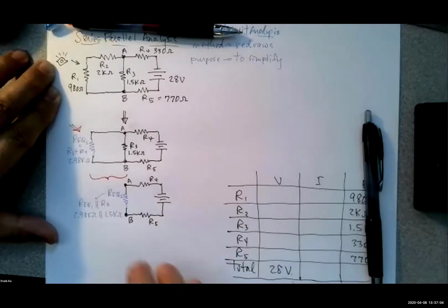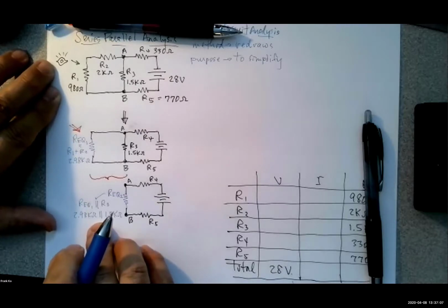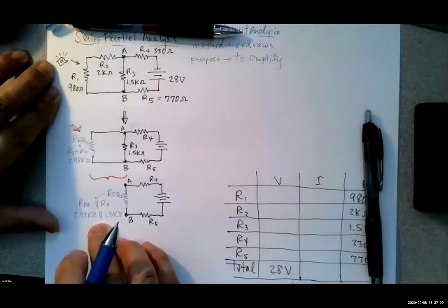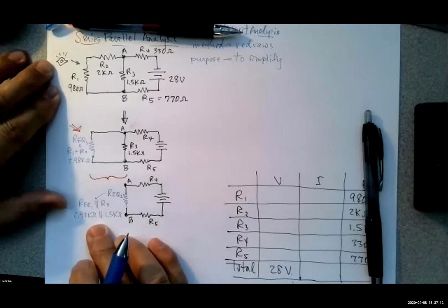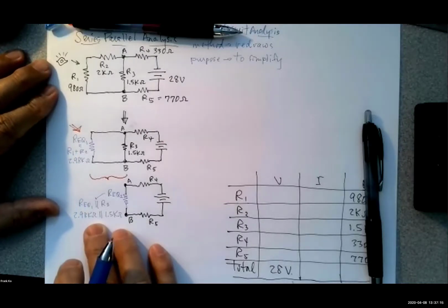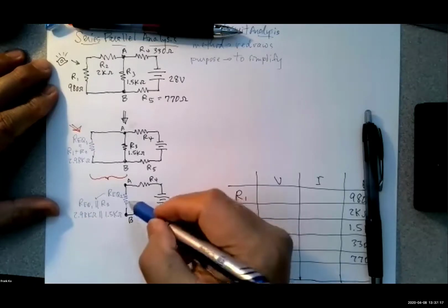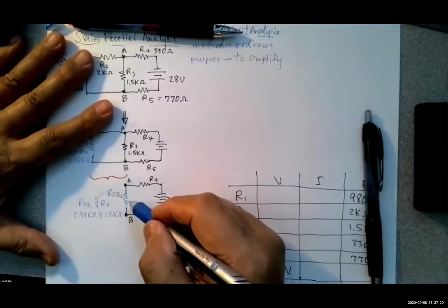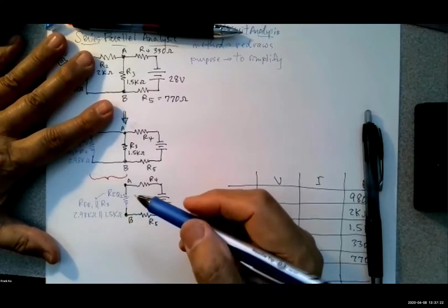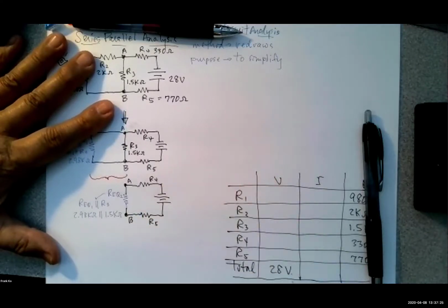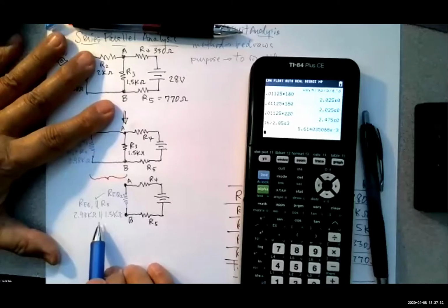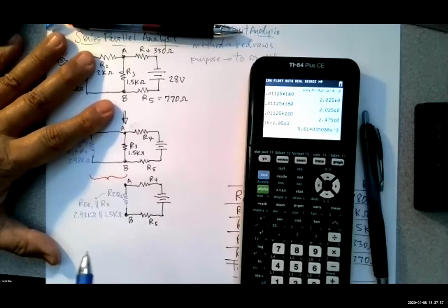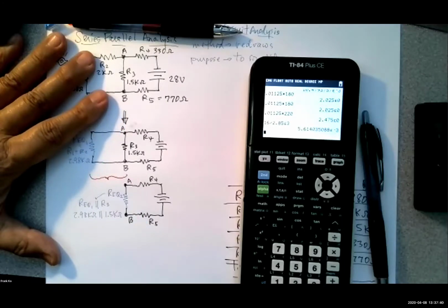So that being said, just off the top of our head, can we guesstimate some kind of a number for this? Question goes to Pauline. The result of these two in parallel to be a single equivalent resistance should come up to approximately some kind of a number. What might that be without calculating? That would be 3.4 kilo. They're in parallel now. What do we know about parallel resistance, the total of a parallel bank?